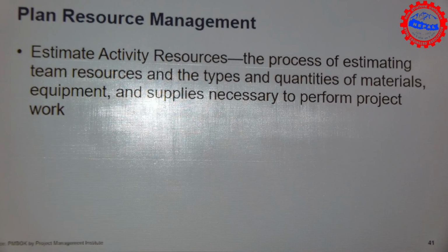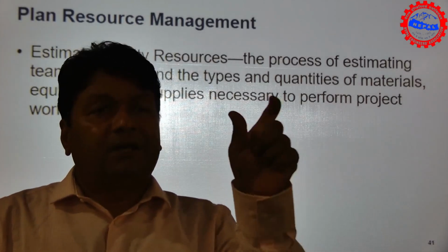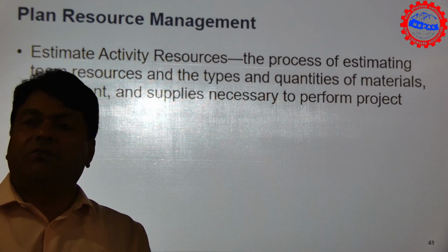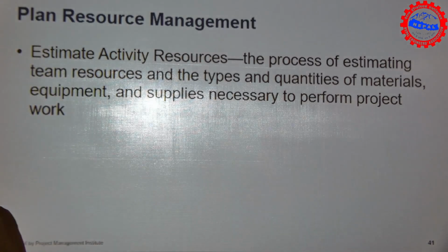Anyway, no need to worry about that. It is all about the quantity and the productivity. Here it's all about the productivity. Per hour, how many cubic meters? One painter per hour, how many square meters are they going to do? Where does that information come from? That is called the archive. If the company has different manpower productivity for each activity, I'm sure they have a list or online resources or not. Norms, they already have norms per hour. So norms will give you some idea to calculate, plus the risk and contingency.